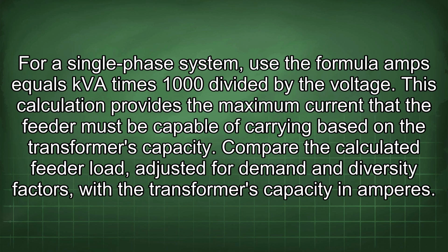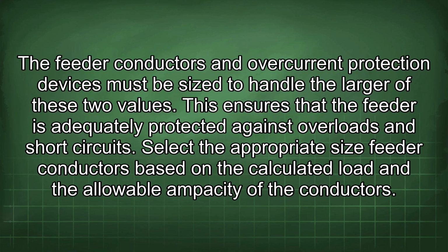Compare the calculated feeder load, adjusted for demand and diversity factors, with the transformer's capacity in amperes. The feeder conductors and overcurrent protection devices must be sized to handle the larger of these two values. This ensures that the feeder is adequately protected against overloads and short circuits.